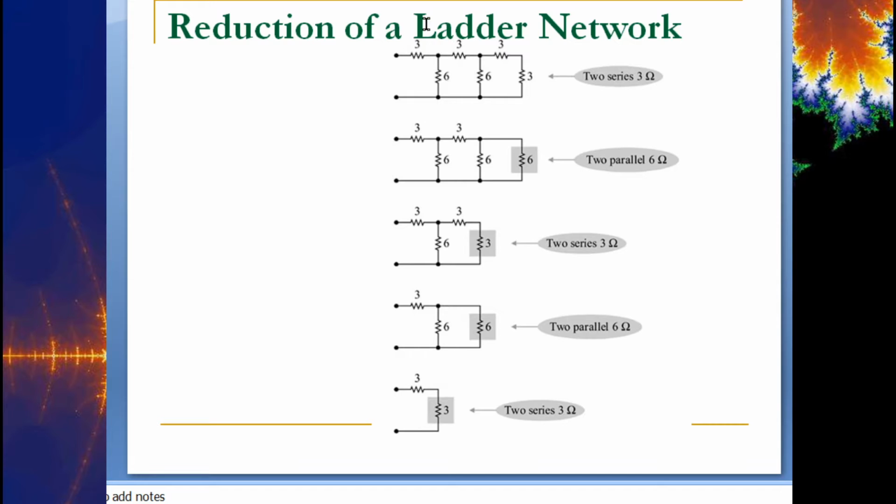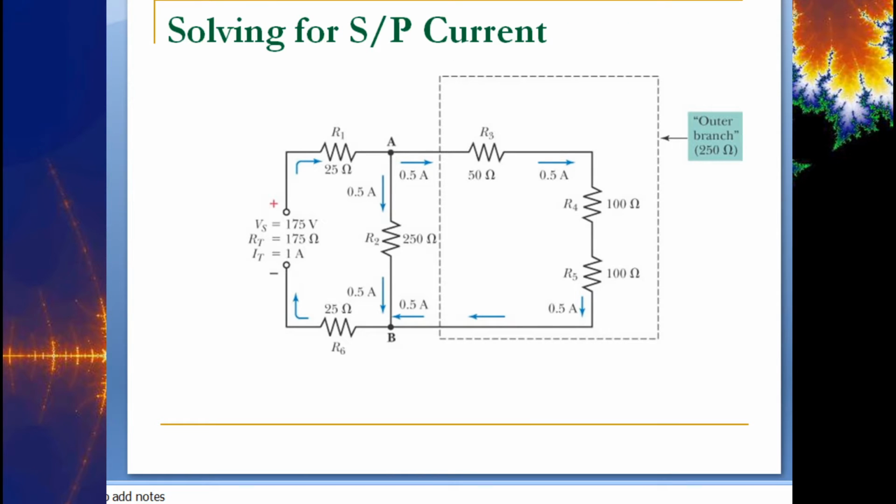So you might not be able to tell that if you just look at the circuit up here. Now I know that this is an R-2R ladder, and so I would have known that there's 6 ohms if I knew what R was and what 2R was. But I will do a few of those examples as well. And I think this is probably a good time to get off the PowerPoint and go straight to the board.